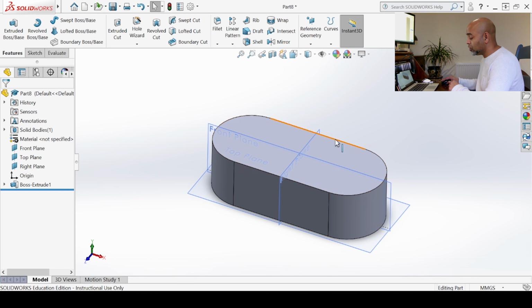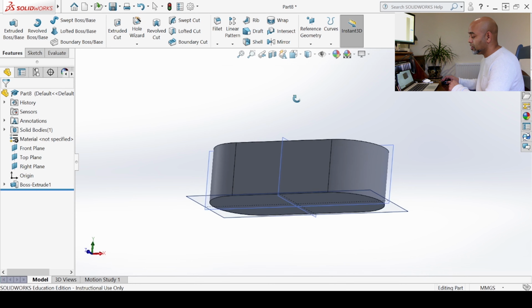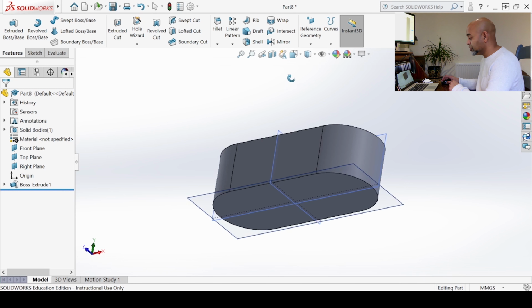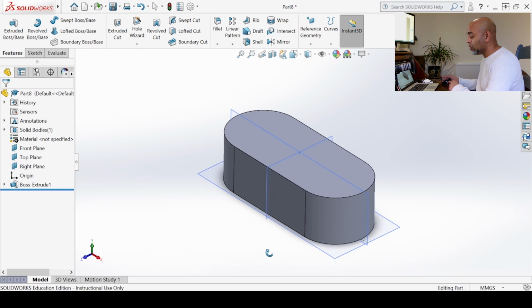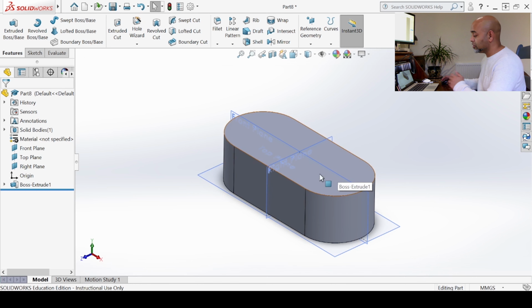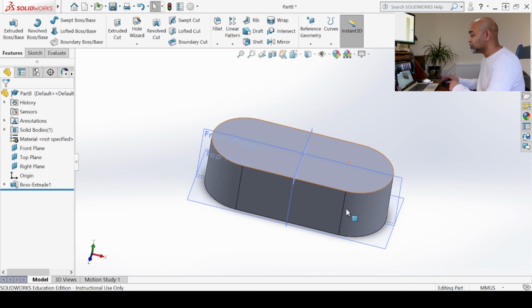What I need to do is locate a flat surface wherever I can start sketching. Now this probably might be good new knowledge to you. You don't really need to rely all the time on planes to sketch on. You can actually use the flat provided by the recently created solid as your sketching plane too. So in this instance, let's say I wanted to sketch something on this flat surface there and use that profile to drill through all the way out on the other end. So I can do exactly that.